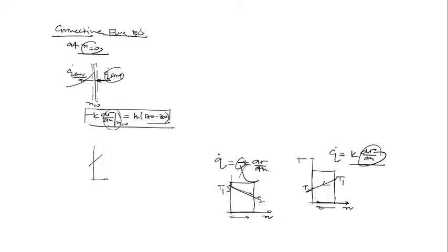Only in the case of increasing x does temperature decrease. Yes or no? But in this case, with increase in x, temperature increases. That's why I have the plus sign. Is this clear? Yes or no? And you can see if dt upon dx here is positive, then q is negative, and that indicates you, sorry, here dt upon dx is what? Tell me. As x increases, temperature increases.